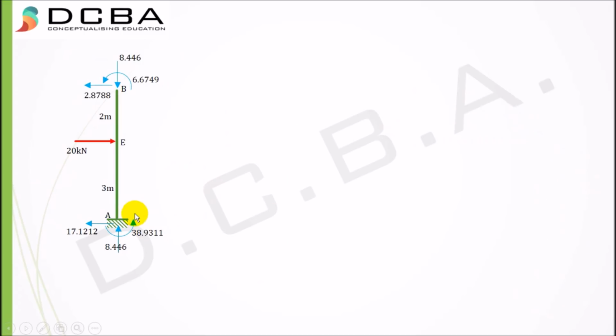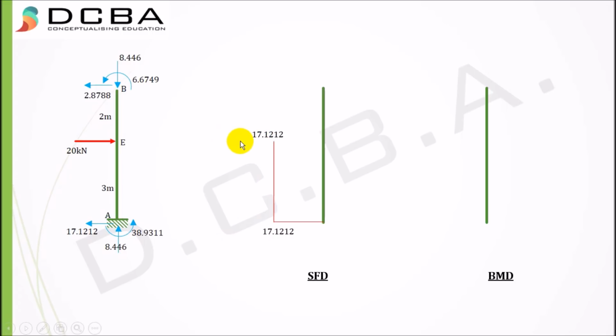Now let's draw the SFD and BMD. The shear force diagram for this would be 17.1212 upwards, then constant till point E, then 17.1212 minus 20, I get around 2.8788 downwards, then again constant till here, and this is your SFD. Your BMD would be 38.9311 downwards, then I am finding the BMD at point E: 17.1212 into 3 minus 38.9311, I get 12.42, right? And then 6.6749 joining it. So this is your BMD for member AB.